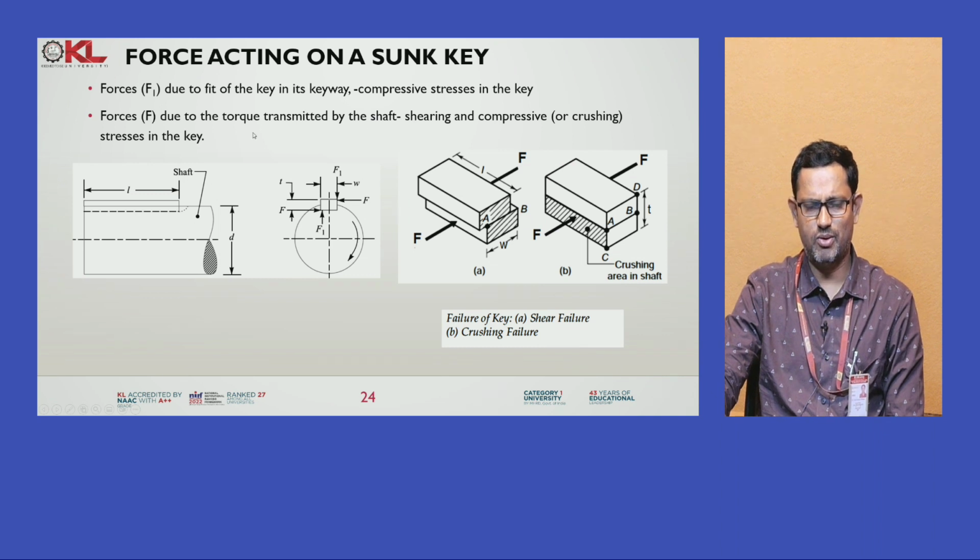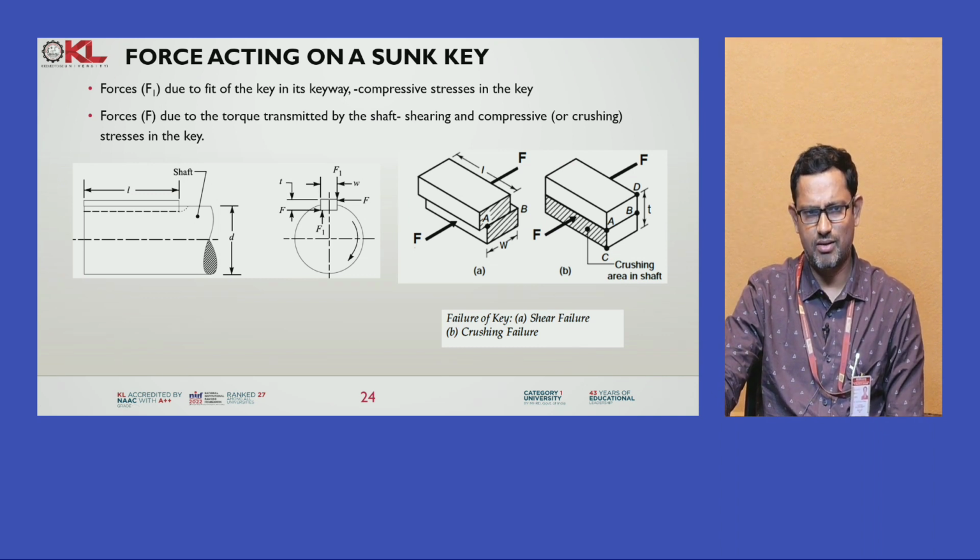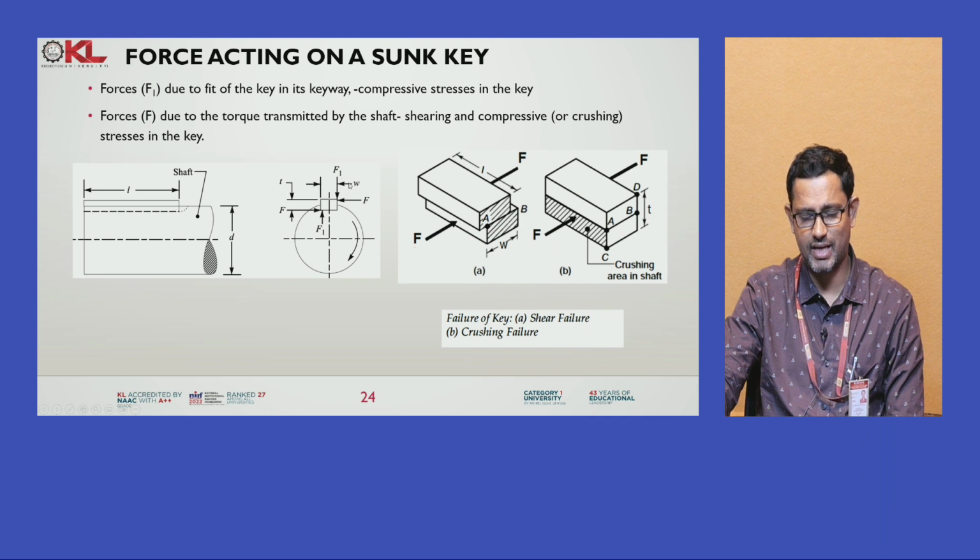Now we know what dimensions we have to take for designing a sunk key. But what are the stresses or loads that will act during the running conditions? If you see here, this is the key, and here we have force F as well as F1. This F is due to the torque transmitted by the shaft. Since the shaft and the key are integral parts, the key should also transmit it. One of the functions of the key is to transmit the torque.